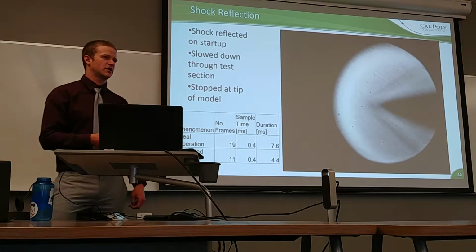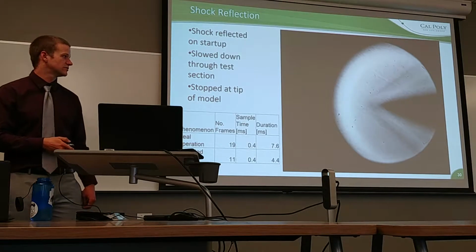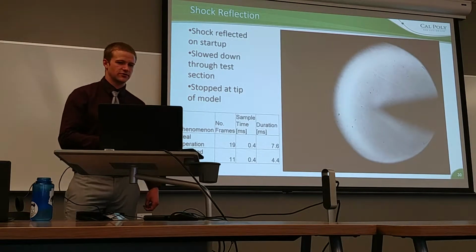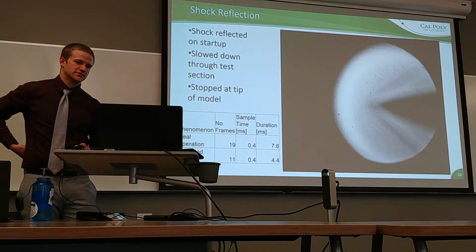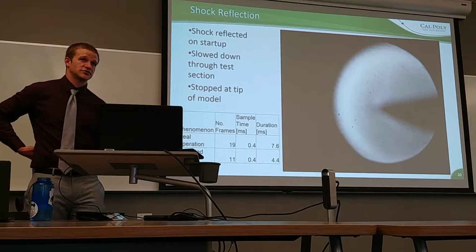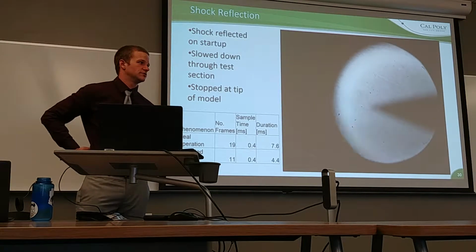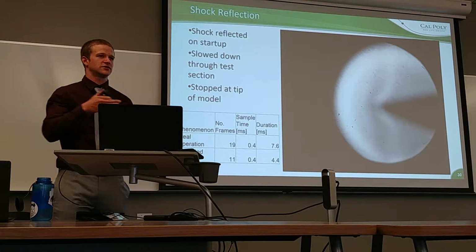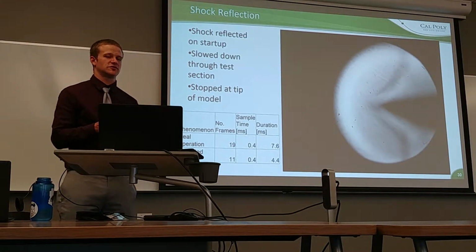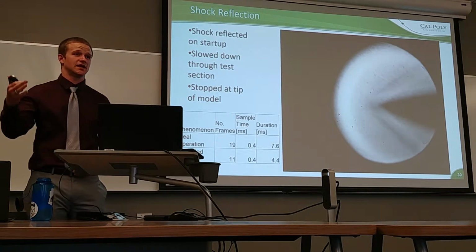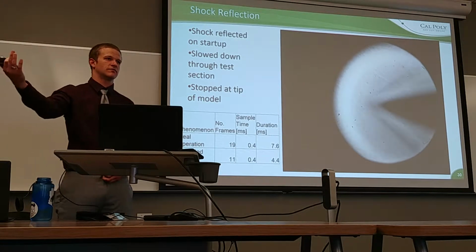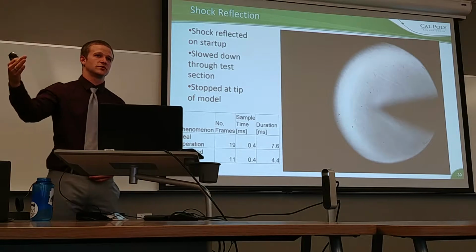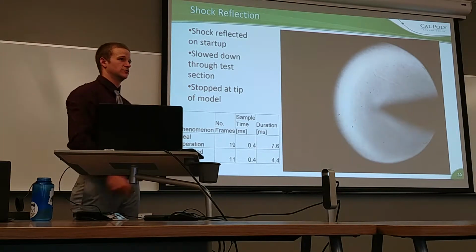One thing that you may have caught, it happened pretty quickly in that video, but it slowed down a little bit here. This is on slide 30. On startup of the nozzle, flow went into the chamber, expanded, and eventually hit the wall, and then a normal shock was forced to form and propagate back through the chamber.